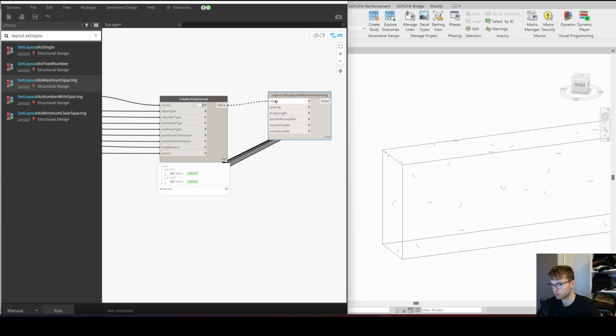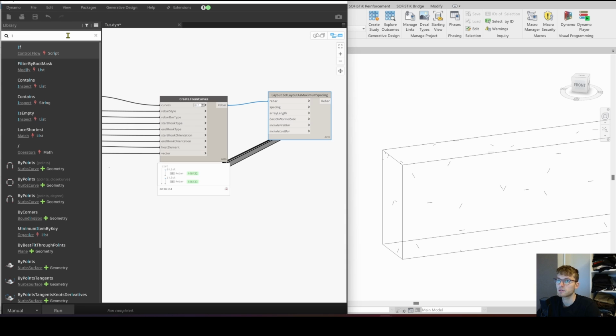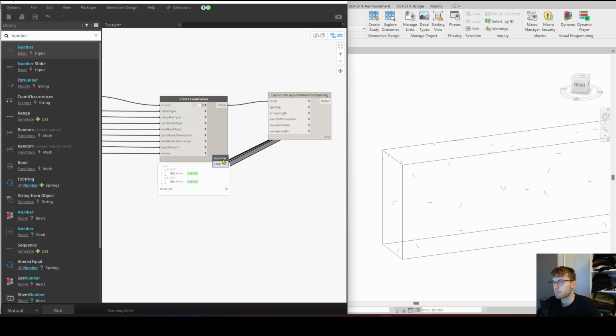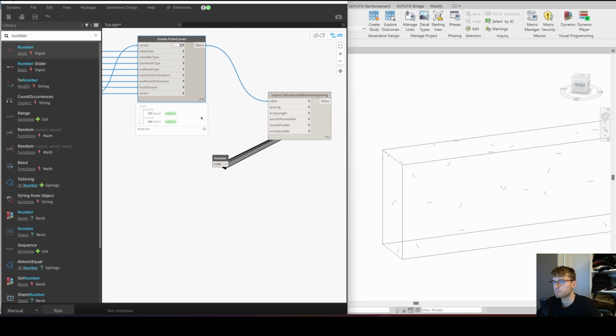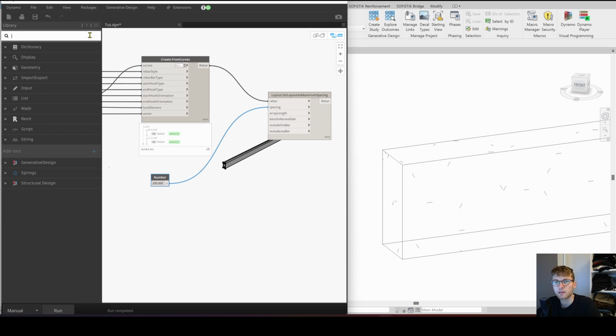So now I'm gonna select my 2 rebars. I want to have the input of a spacing. So let's say we want to have a number input here. Oops. And that is in millimeters. So for now we want 200 millimeters. And again, this number could also be automated with calculating some distances between the edges, but again, we don't want to explode the scope of this tutorial, and also everyone has different use cases.